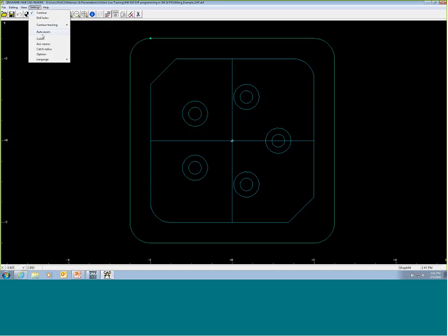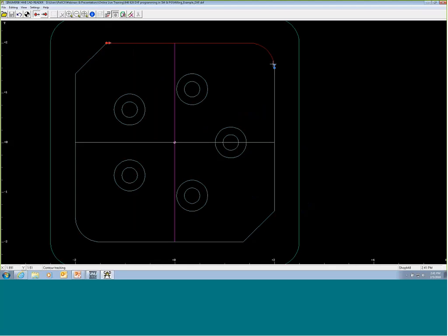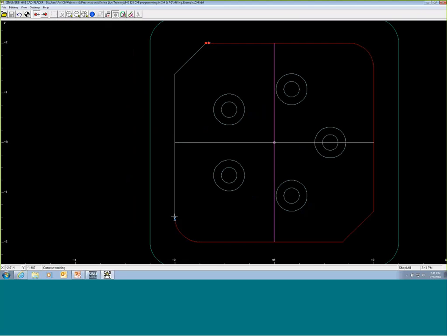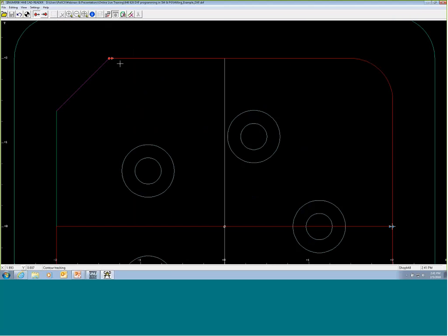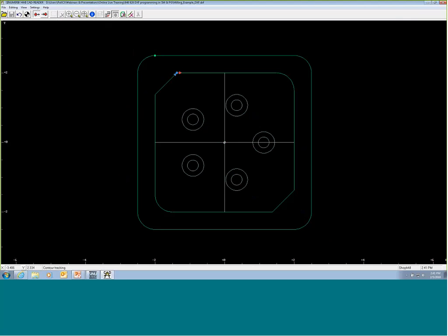Now the other thing that gets handy, especially when you have a lot of detail, a lot of segments in a drawing, once you've picked the intersection strategy or the contour tracking strategy, is the auto zoom. So if you have auto zoom on, just by clicking it, it'll give you a little checkbox right there. Now, as I start to create the shape, it zooms me right to the area in question. Boom, puts me right there. On this part, it's pretty straightforward because it's not that big a part. But if I had something with a lot of detail, it's going to drive me right to that portion where I potentially have a choice in the intersection, and I can click on the appropriate feature.